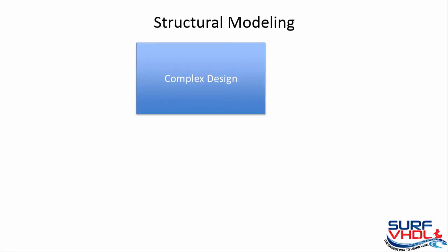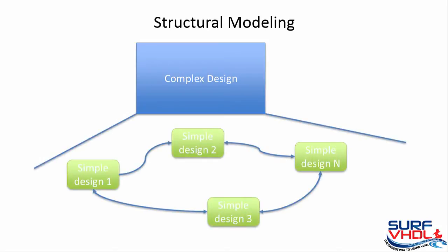The term structural modeling is the terminology that VHDL uses in the modular design. I mean, if you are designing a complex project, you should split it into two or more simple designs in order to easily handle the complexity. The benefits of modular design in VHDL are similar to the benefits that modular design or object-oriented design provided for higher-level computer languages.